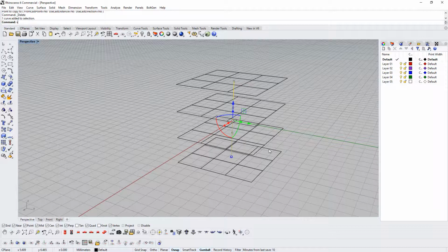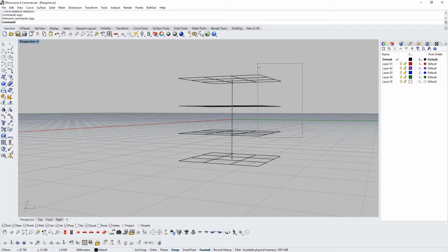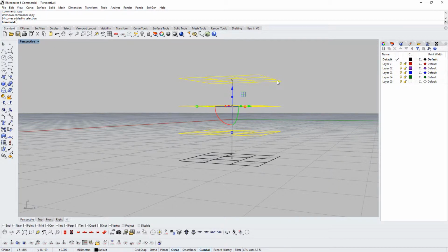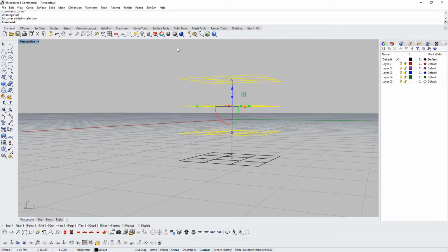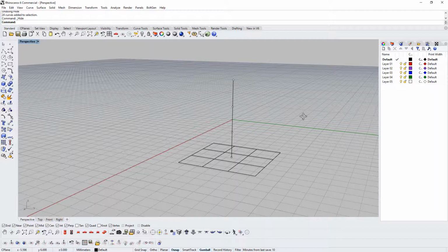Alright, and so the center point here, we know this needs to go everywhere, right? So we need to go ahead and copy that center line. And what we can do is probably hide these top ones. Control H hides. Or we can highlight them and hit this little light bulb right here, right? And that hides it as well.